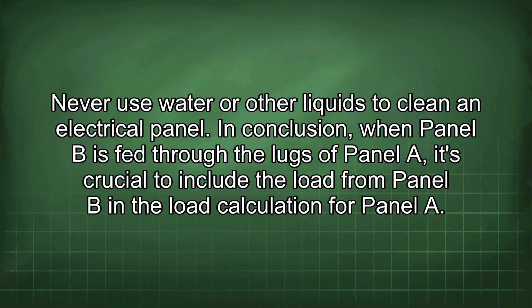In conclusion, when panel B is fed through the lugs of panel A, it's crucial to include the load from panel B in the load calculation for panel A.